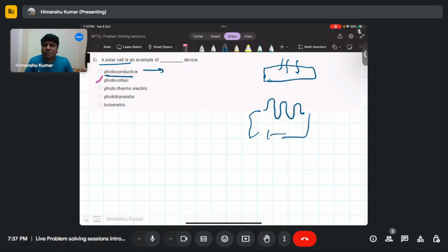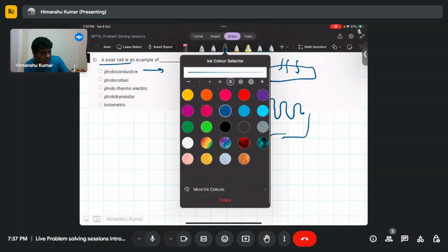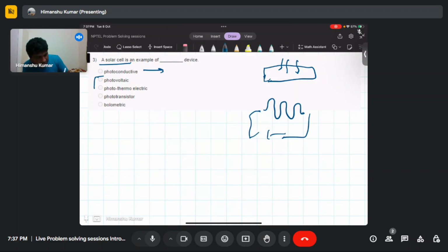When you put light on it, the resistance of the photoconductive device changes, which leads to a change in the voltage, and you can use that for sensing. The other type is photovoltaic, where you generate a voltage depending on the number of photons incident. Photoconductive devices can't operate in zero bias condition, because they do not generate any energy.